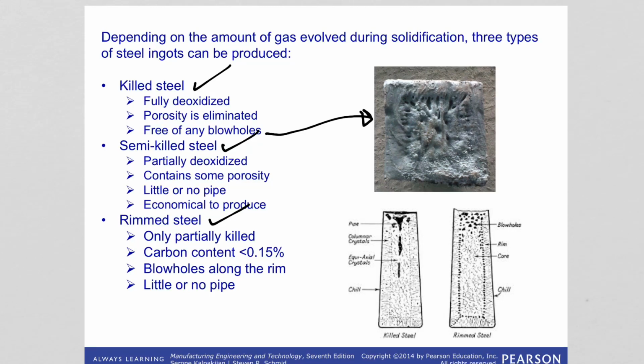However, of course, going from a liquid to a solid, there will be shrinkage in the structure. And because of this shrinkage, the ingot will develop a pipe at the top. We also call it a shrinkage cavity. It has the appearance of a funnel-like shape. You can see it here in this image. This pipe formation is basically because of shrinkage. So we can add this one also.